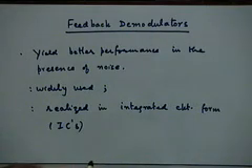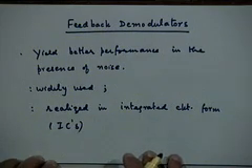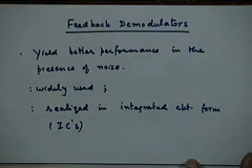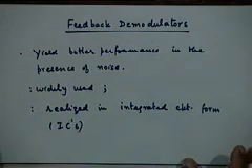The reason for that is typically in these kinds of feedback demodulators we do not use any inductors. The balanced discriminator that we discussed so far is based on the use of tuned circuits, staggered tuned circuits. The two slope circuits that we have talked about will be typically realized by using the linear portion of the frequency response of a resonant circuit, a parallel LC circuit, whereas there will be no LC components in this realization.